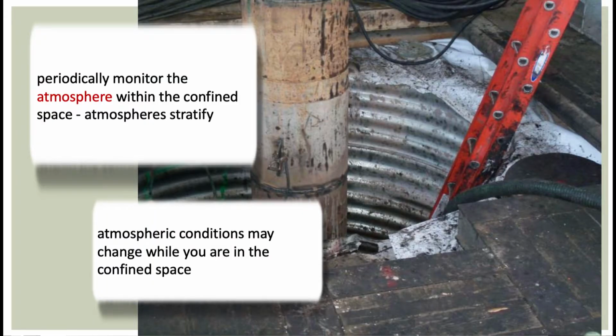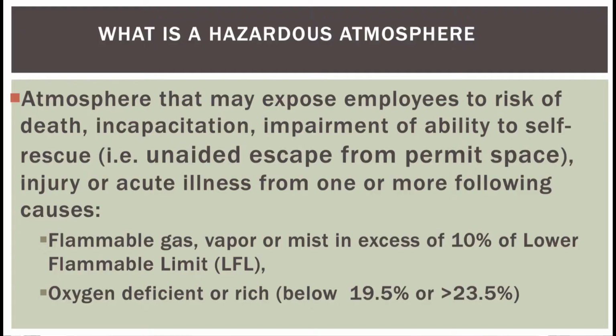So the standard also talks about periodic monitoring in atmospheres, and to monitor the whole layers within the container, because atmospheres will stratify or separate. And also atmospheric conditions can change when people are in a confined space, especially if they're doing work or you have a mixing effect. So the gases when you're in a confined space could be mixed around, right? Because you're in that space together.